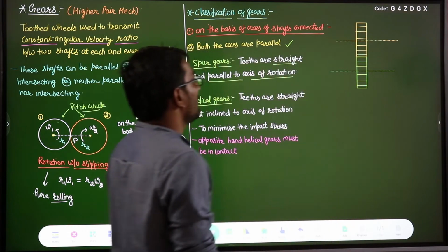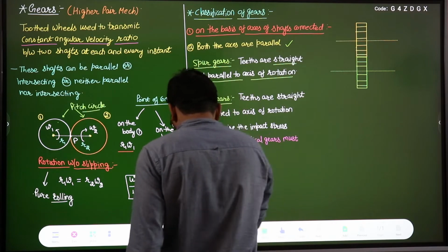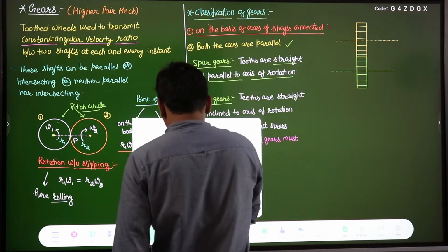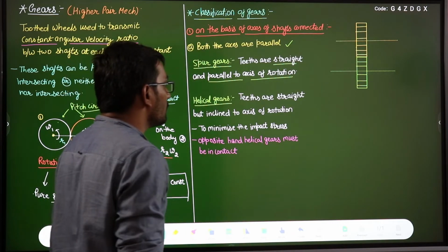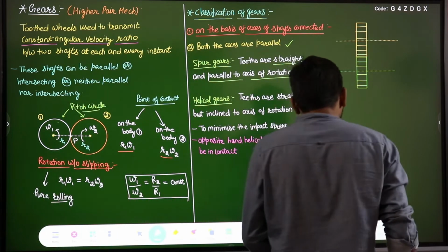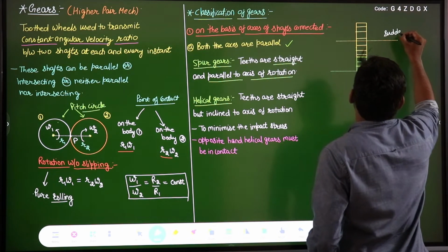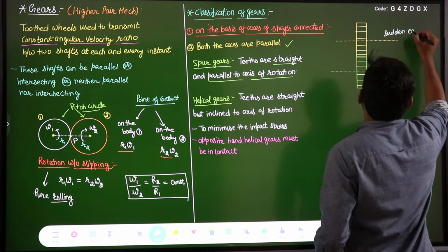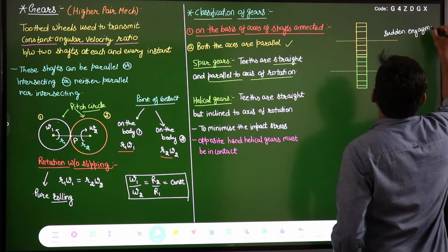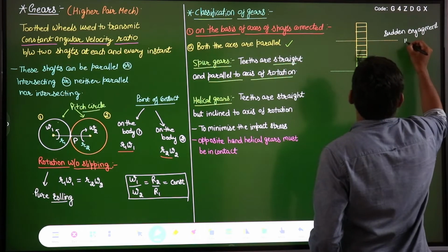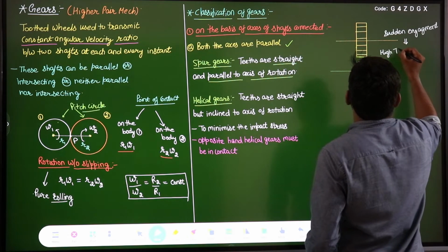These are the straight gears on gear 2. Now, in this case of this spur gear having parallel teeth, or straight teeth parallel to the axis of rotation, because of the sudden engagement and disengagement, there is sudden engagement of one tooth with the other tooth of the other gear. Because of this sudden engagement, very high impact stress will be generated.